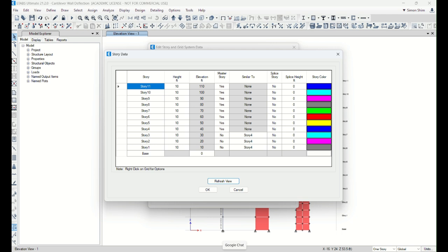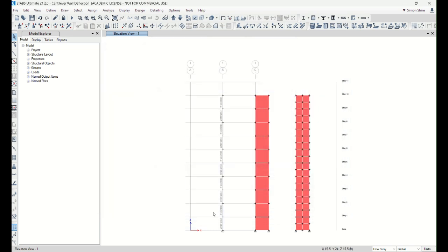Because they already set this up, I have the total floor information, but if you open a blank one, it may have only one story. You need to add copies and define the number of floors you need, and then type in each floor-to-floor height. We're going to get into that, but this is how to define the building height.